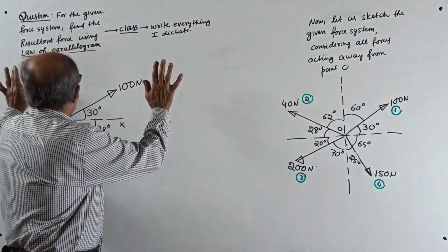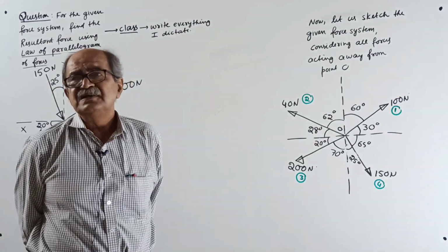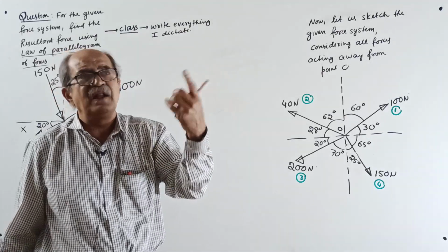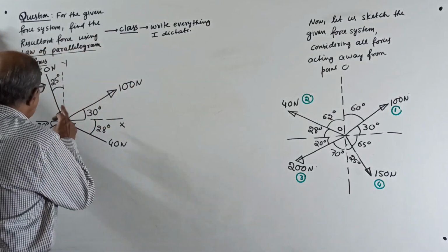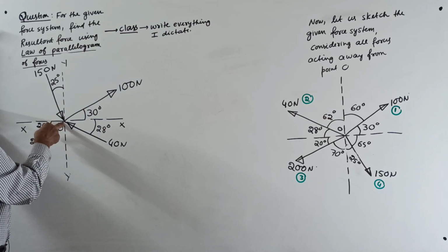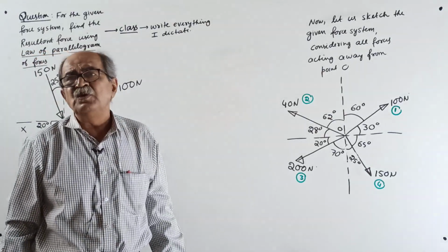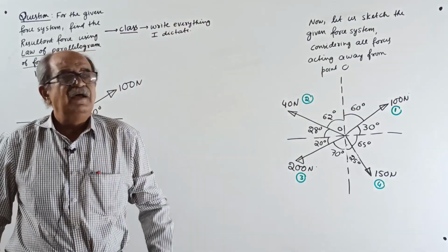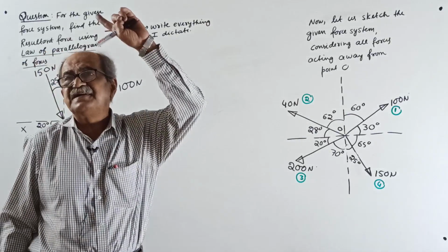As soon as this law of parallelogram of forces is over, I am going to resolution only. First I will tell the principle and then start examples where multiple forces are acting, first concurrent, then coplanar. But when you go to coplanar, line of action also comes. As I told, in a concurrent force system, all forces pass through the point O, one common point. The resultant also will pass through the same point, so you have to find only magnitude and direction. If you want further clarification, wait for some time. When I explain the coplanar force system, then you will realize, oh yes, correct, what he told at that time, now clear.